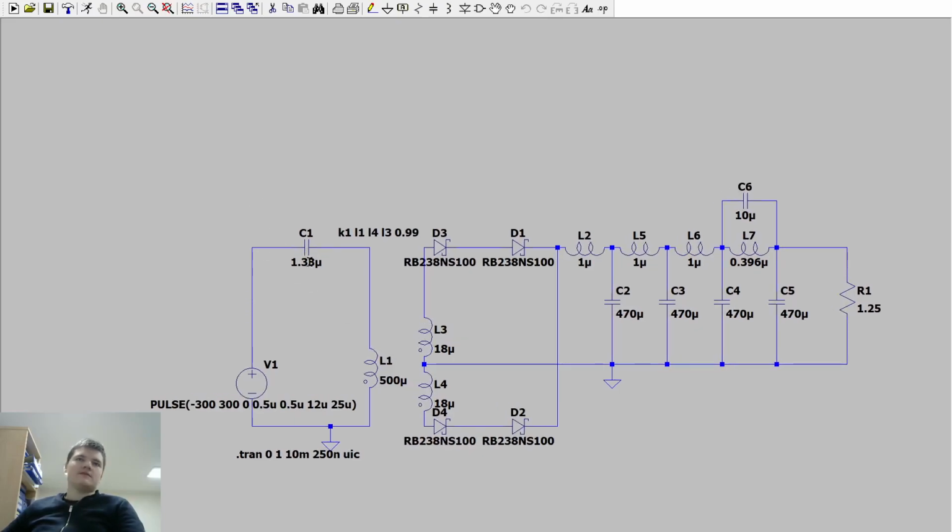As you can see, this is not the usual way those power supplies are built. I think it's called an LLC full bridge topology, and it has, not in parallel but in series, a capacitor that makes this circuit resonant and somewhat more efficient than if there was just a short here.